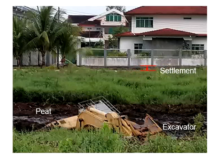One significant problem with the peat is the low bearing capacity, especially when the water content is relatively high. It seems that they are now trying to do the site clearing in order to kickstart a project. Along the way, due to the poor bearing capacity, the entire excavator has now been submerged into the soil due to the inability of the soil to generate sufficient reaction to support the weight of the excavator. These are issues with the soft soil or peat soil.